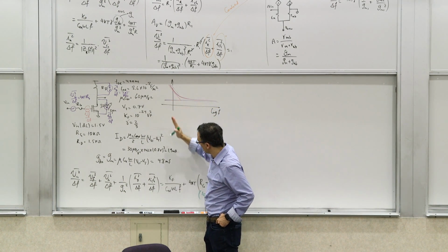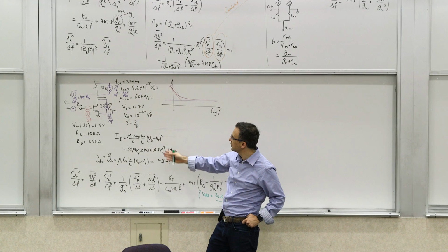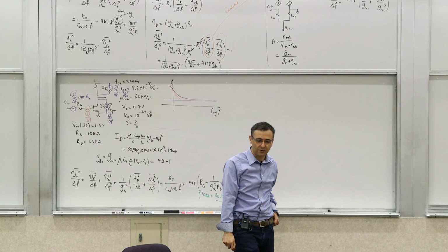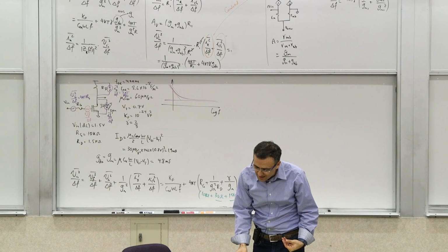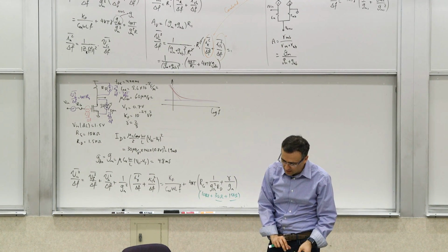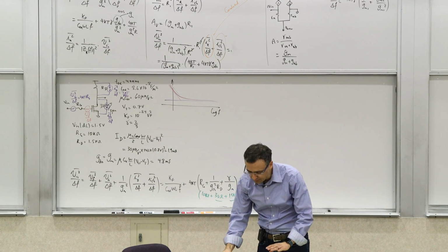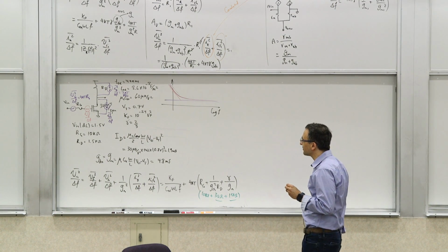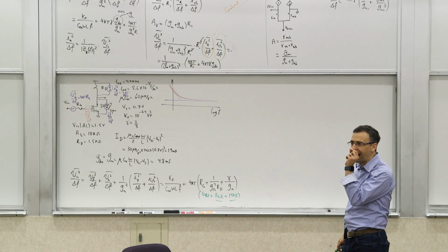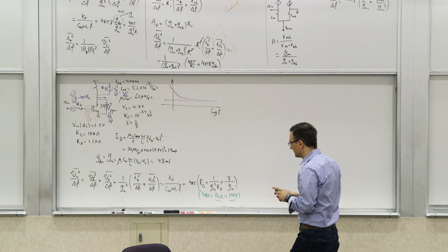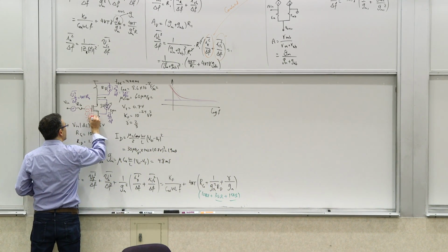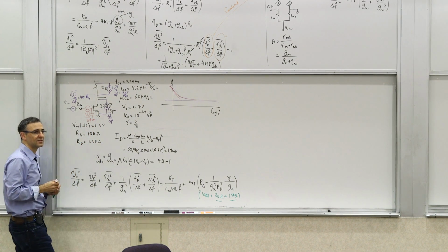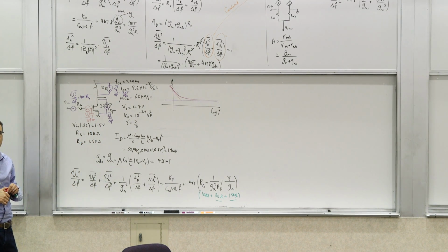The flicker noise, no. The flicker noise is dependent on the W and L, and you can pick some values and calculate them. So that's one thing, but that assumes that there is no frequency response, right? So let's just, to get a feel for something, assume that you have just one capacitor. Let's add one capacitor to the circuit. I mean, we can do more, but we want to see what happens. So let's say you have a gate capacitance here, CGS, or CG, whatever. Let's call it Cin.